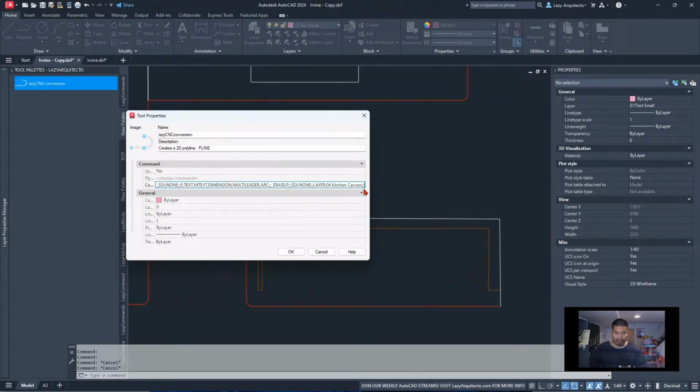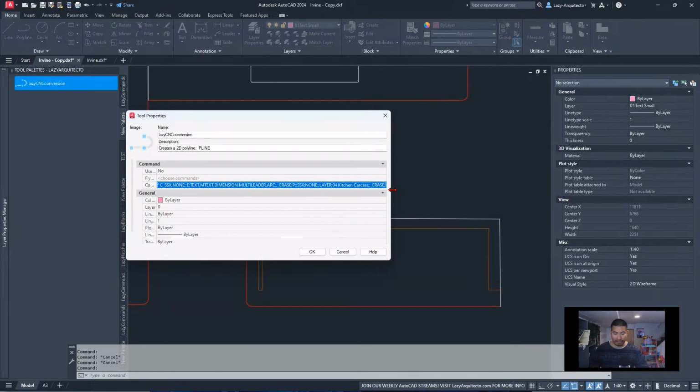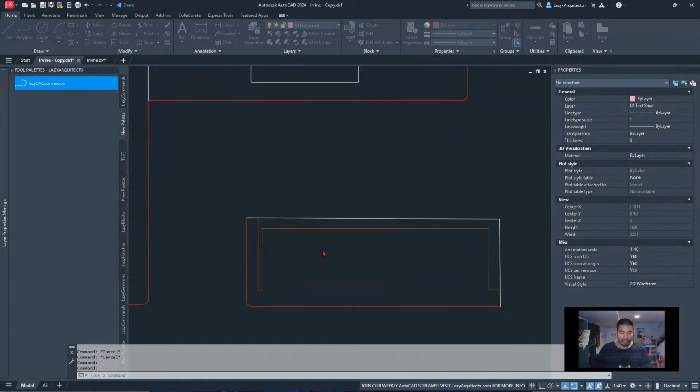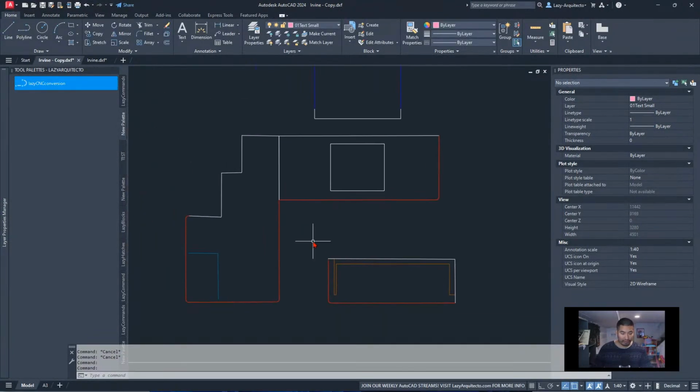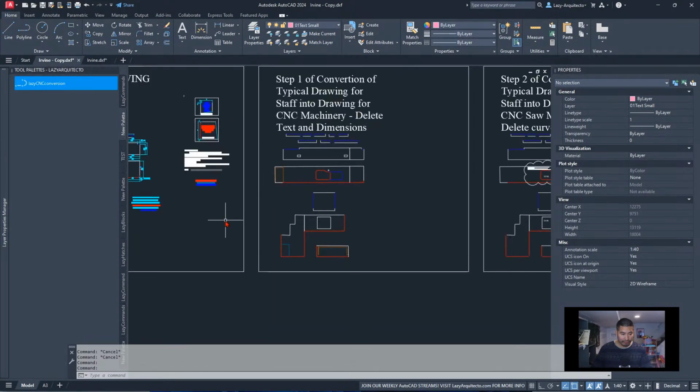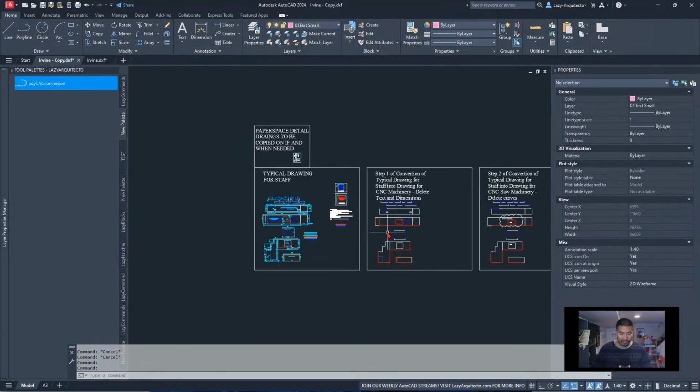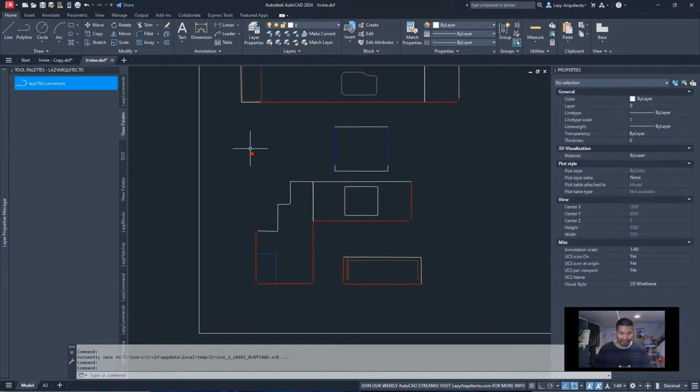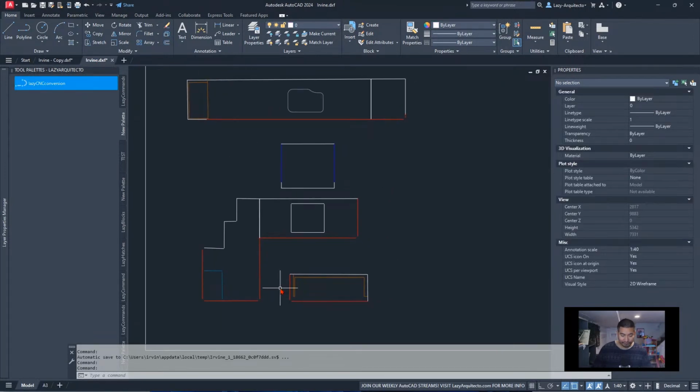I want to erase this layer, so I'm going to say erase and press enter, and then erase what? Erase our previous selection, right? Which was the selection of this layer. So let's quickly test that, to see if it works or not. Of course we don't want to test it right here, we want to test it on this drawing that we have.